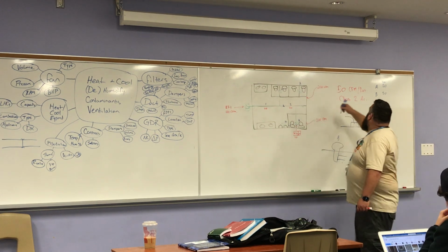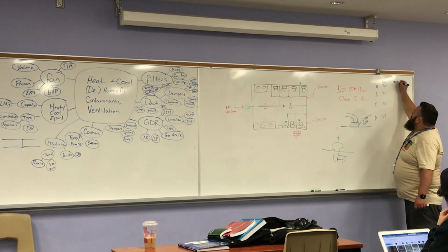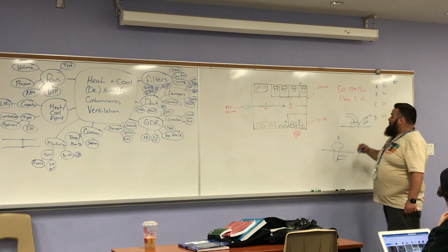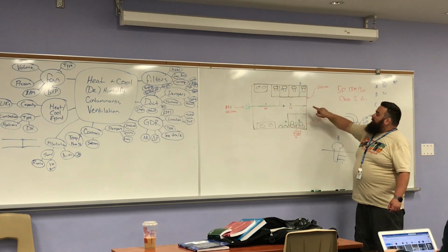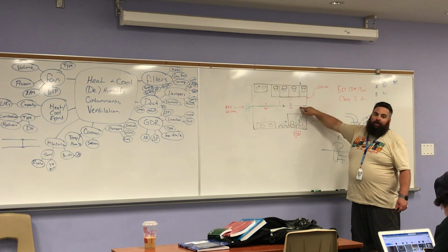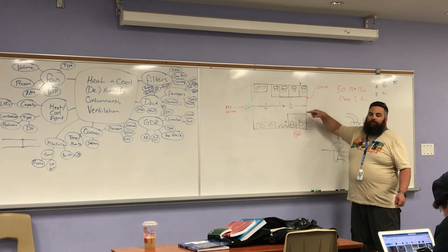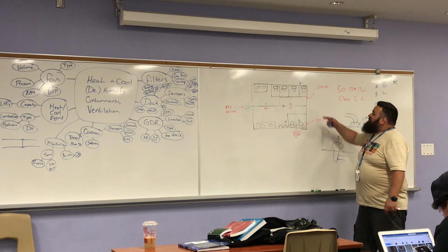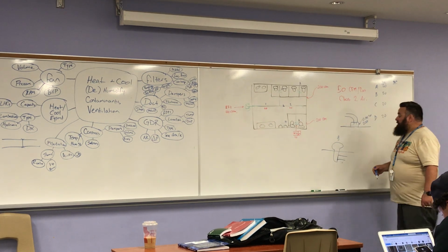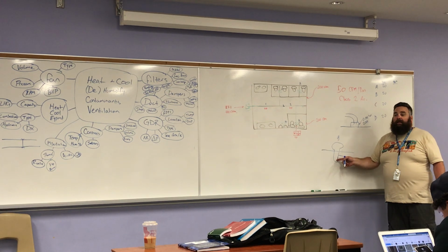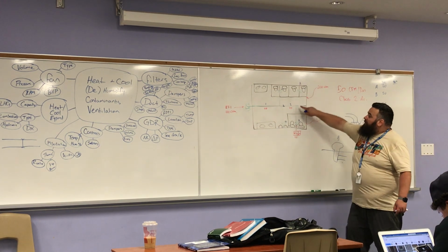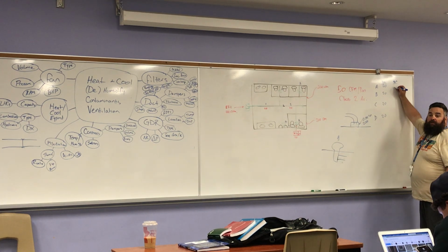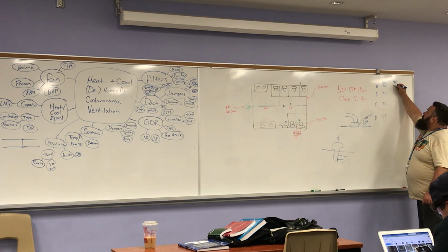You would look at your 90s. How many 90s do I have? For A, I have 1. We wouldn't consider that a 90, we would consider that a takeoff, because there's convergence. So I only have 1 90, and actually let's say I have another 90 here, okay? So I have 1 90 when it comes there, 1 90 when it goes up to EF1. So all of them have two 90s, right? Let's say each 90 is worth 5 feet, so I got 10 feet.